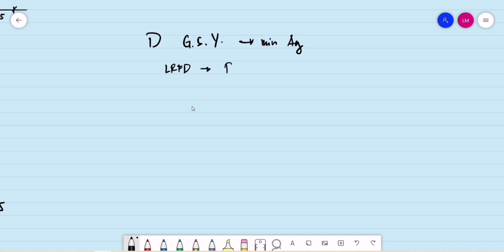So we have Pu less than or equal to φ multiplied by Pn, or less than or equal to φ, a reduction factor, multiplied by Fy, then multiplied by the gross area. So if you are looking for the gross area, that is the ultimate load divided by our reduction factor φ multiplied by Fy.